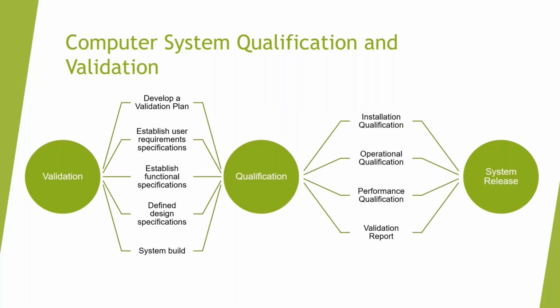And then in terms of the actual qualification or the validation of the system, there's various steps that the validation should have gone through depending on what type of system it is. So I want to know, first of all, which systems have they followed? Have they got a GAMP5 structure in terms of defining how they'll perform a computerized system validation? And part of the validation phase is there should be a validation plan which details the scope of use, the validation approach, the roles and responsibilities, and the acceptance criteria that they're going to use.